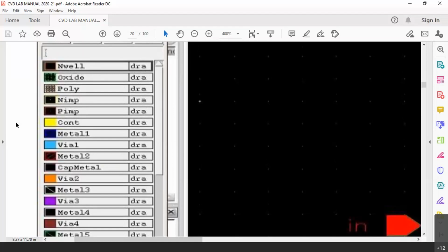So here, when we make a MOSFET, we have a channel below and we have a gate above. Now gate contact is by means of polysilicon. Below we need a channel to be induced. Now in between there is an oxide layer.